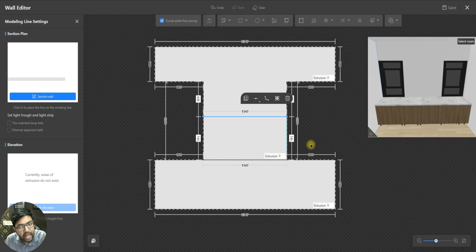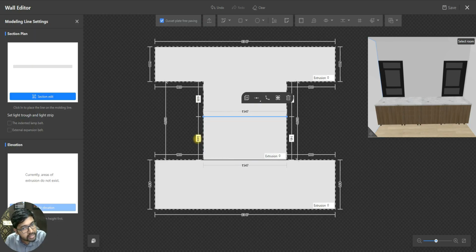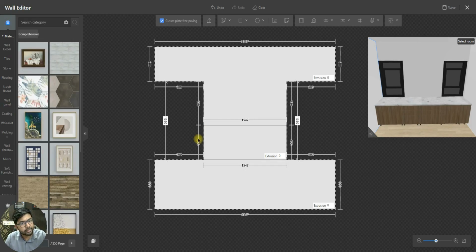So in my case here, I'm looking for a backsplash height of 600 mm. But right now if you notice, the backsplash height is 745. Click on this clearance and edit it as 600 mm and press enter. So now your line has precisely moved to a distance of 600 mm from your face point. So now you divided the surface.